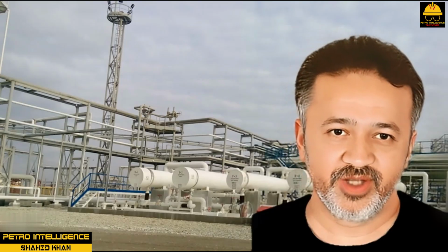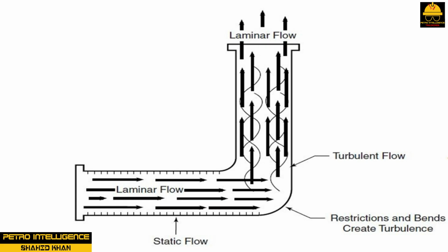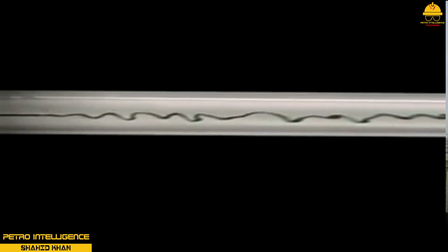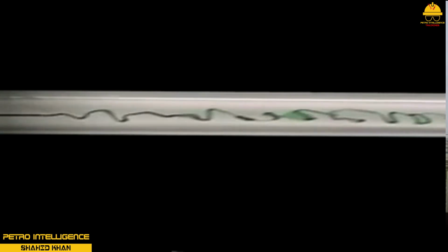Laminar and turbulent flow. Two major classifications of fluid flow are laminar and turbulent, as shown in the picture. Laminar or streamline flow moves through a system in thin cylindrical layers of liquid flowing in parallel fashion. This type of flow will have little, if any, turbulence, swirling or eddying, in it. Laminar flow usually exists at low flow rates. As flow rates increase, the laminar flow pattern changes into a turbulent flow pattern.